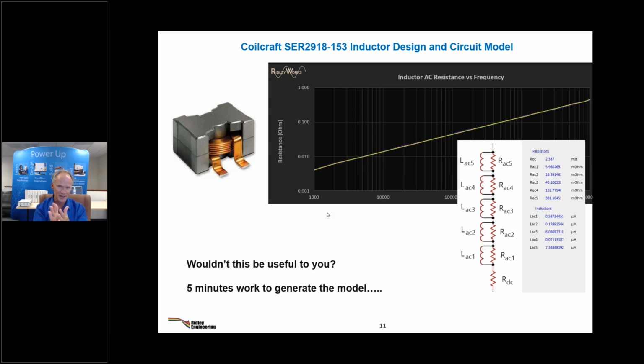It's nice to space the flat planar windings out a little bit. Also, when you wrap foil around the bobbin, if you don't do them with the flat foil and you do it with normal wire, if you use thin wires, don't cram them up against each other. You use a thin wire and then lots of insulation to fill the space before you get to the next one. And then you get low capacitance and low RAC as well.